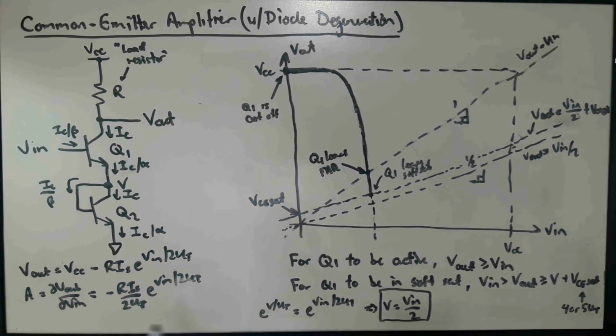Okay, so this model will not describe what's going on with the actual curve, the voltage transfer characteristic, beyond this point. Okay, all bets are off. I'm not going to say what actually would happen here. You can obviously fire up LTspice and put the circuit in LTspice if you're curious to see what might happen in the circuit, but suffice it to say that this prediction from the model that this continues plummeting down here at an increasing rate is not going to be what describes the behavior of the circuit. Okay?